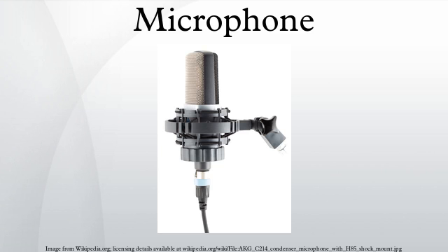Some microphones for this reason utilize multiple membranes for the different parts of the audio spectrum and then combine the resulting signals. Combining the multiple signals correctly is difficult, and designs that do this are rare and tend to be expensive. There are, on the other hand, several designs that are more specifically aimed towards isolated parts of the audio spectrum. The AKG D112, for example, is designed for bass response rather than treble. In audio engineering, several kinds of microphones are often used at the same time to get the best result.